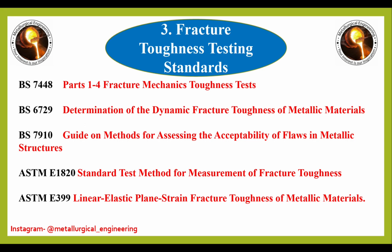These are the different standards for fracture toughness, and what we commonly use are these two: the first one is ASTM E399, and the second one is ASTM E1820. The empirical formulas required for evaluating fracture toughness of metallic materials we obtain from these two. And there are some other standards, but we don't generally use these.